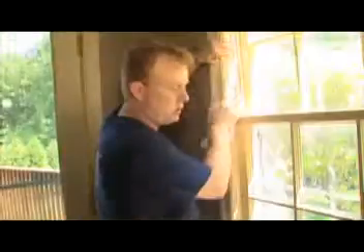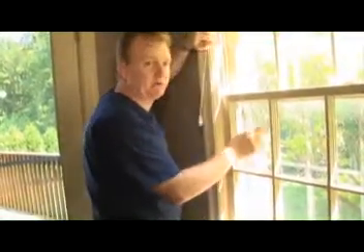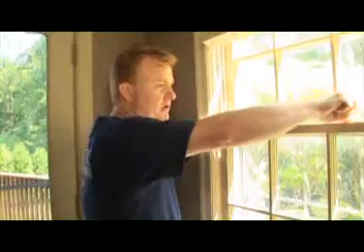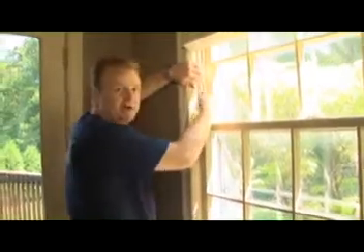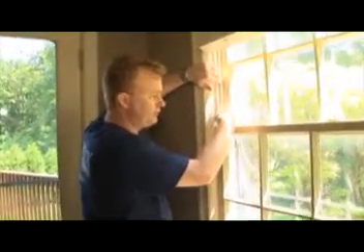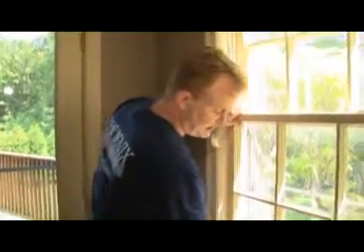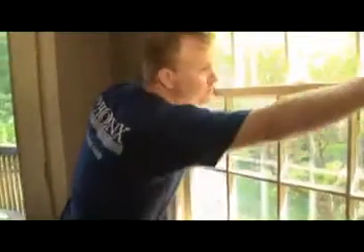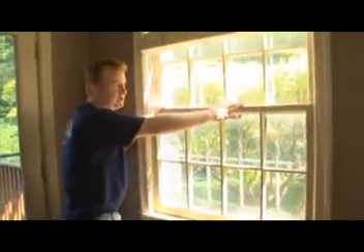We're going to check all the windows in each room of the house to see how leaky they may be. They're older windows. They do have storms on the outside, which does help reduce air infiltration. This window appears to be very tight. I'm not getting a lot of airflow through the tracks, which is a normal spot where air will flow through a window. So even the fact that this is an old window, it's still sealed very well, and is not necessarily a reason to replace the window based on air infiltration.